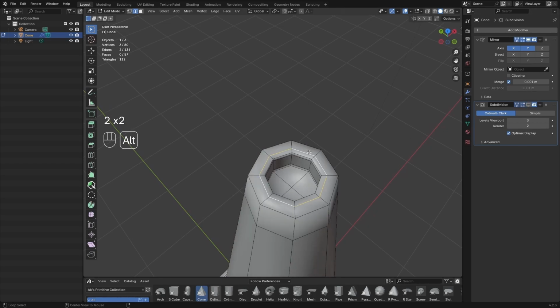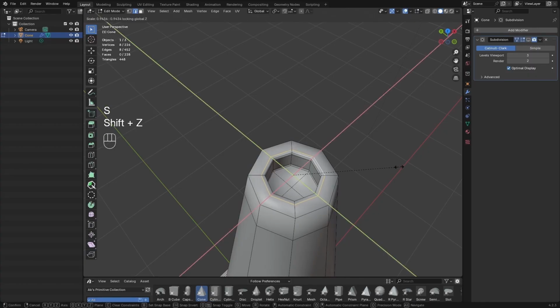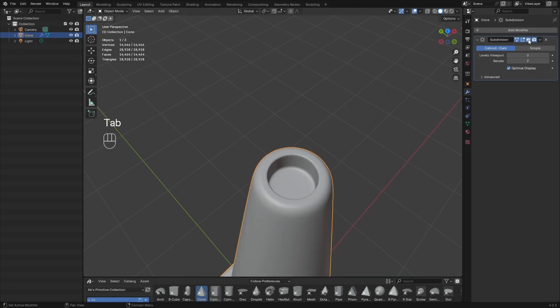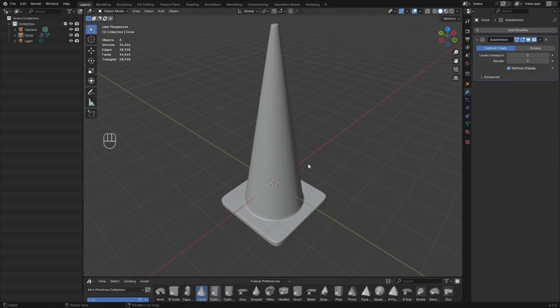And once I'm happy, I'm going to go ahead and select that edge that we have there in the middle, and I'm going to shift that. But before I do that, I'll go ahead and apply a mirror modifier and then adjust the location of that loop. So I want a tighter corner on the inside, and so I've gone ahead and done that.